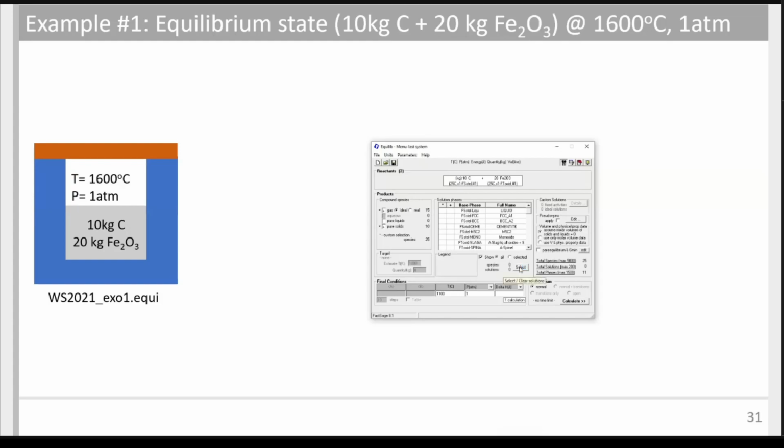By default, if I click on select and select all solutions, I'm going to come up with a phase selection that is appearing here. Notice that some options in this square are I and J, which help the software to define the equilibrium state when miscibility gaps are present. By default, you see here that there are options to consider this potential immiscible behavior.